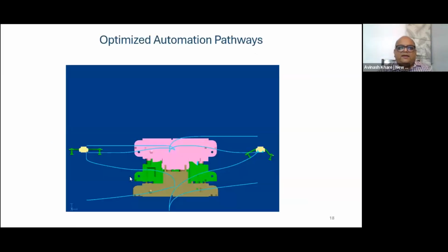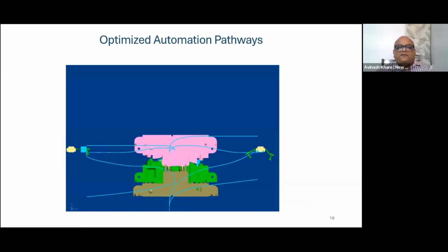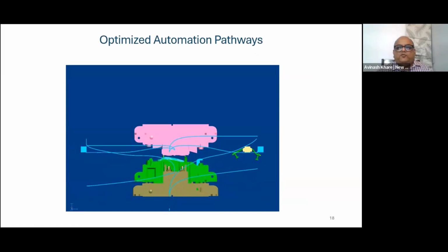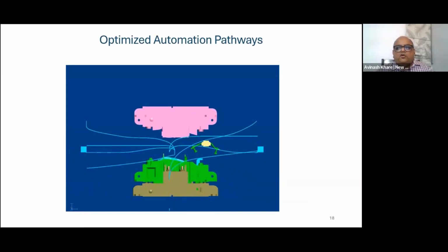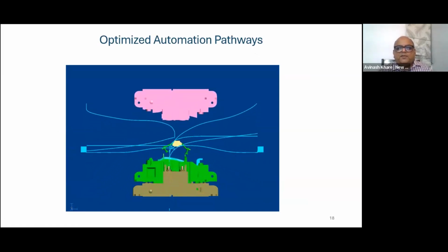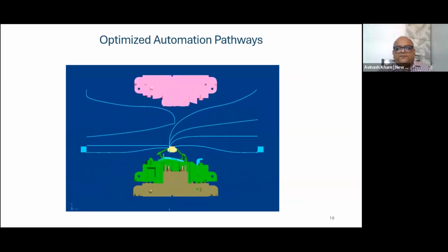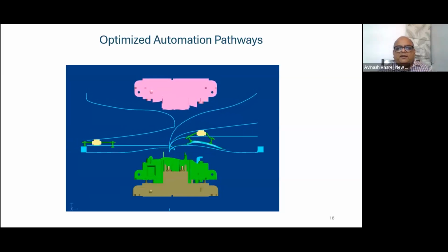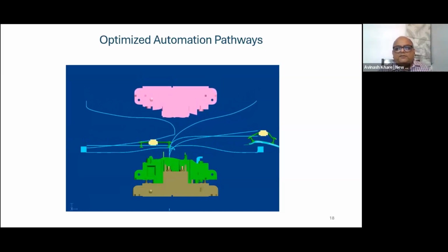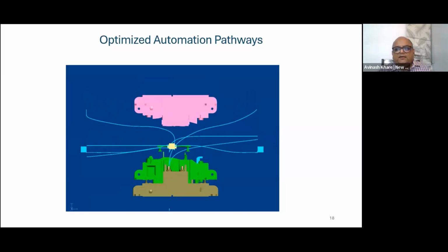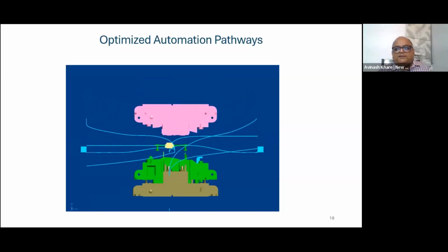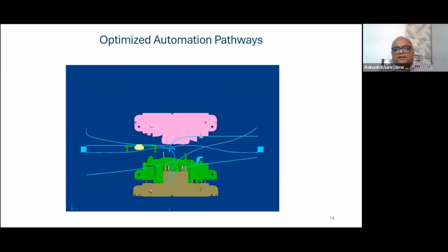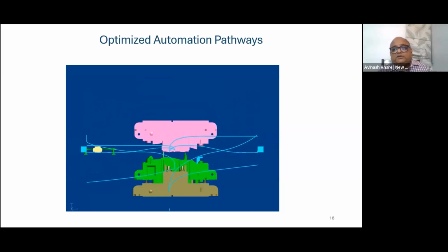And lastly, the robot has to do this function. Now, ideally, the press line never stops. So the upper die will always be moving. The robot from the next press has to come, has to pick up the part from the previous die, move it to the next die. You see the upper die is not stopping anywhere. And from the previous press, the next robot comes. It has to keep the next part. And you see it escapes with a whisker. Otherwise, the robot will get crushed in the die. Right? It is optimized to this level.